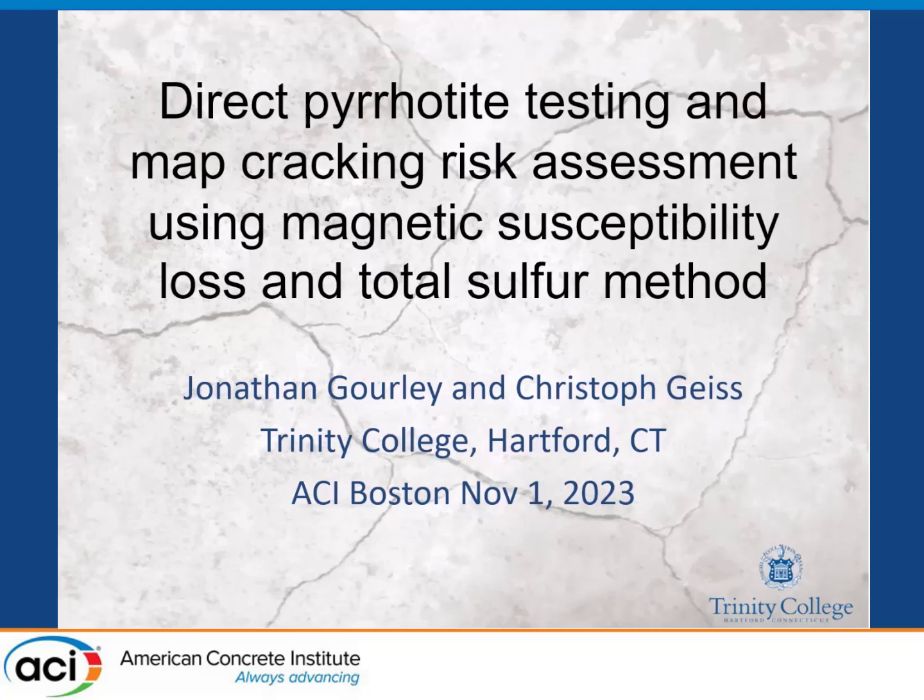My name is Jonathan Gourley, and my co-author, who is in attendance, is Christoph Geis. This presentation will focus on our method for testing for pyrrhotite in home concrete and rock samples as well, and how we estimate possible safe thresholds of pyrrhotite and assess risk using logistic regression models.